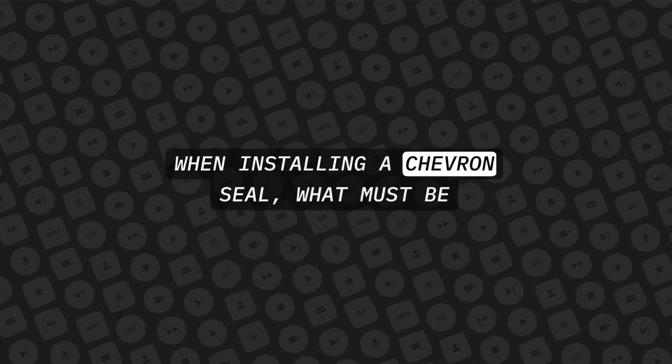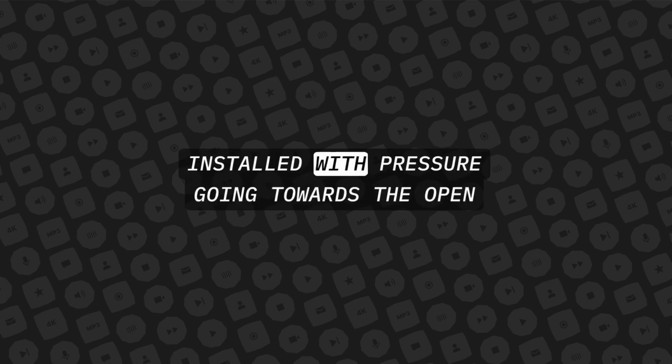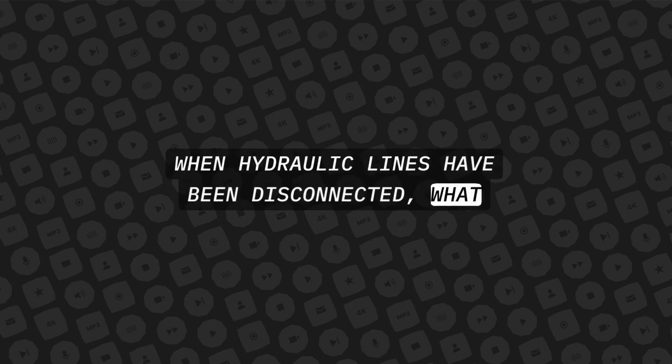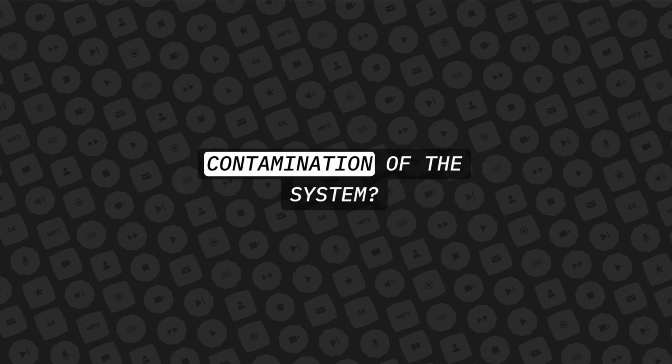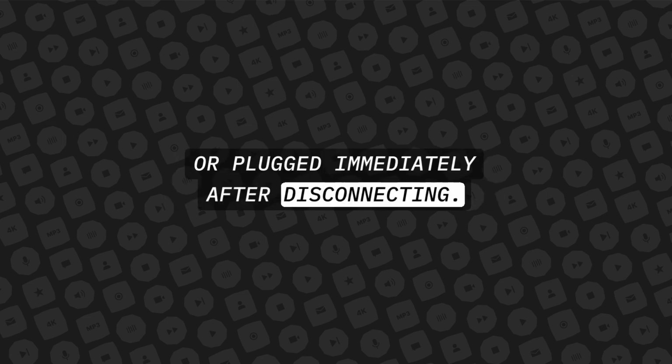When installing a chevron seal, what must be considered? A chevron seal is directional and must be installed with pressure going towards the open side of the seal. When hydraulic lines have been disconnected, what precautions should be taken to prevent contamination of the system? All hydraulic lines and fittings should be capped or plugged immediately after disconnecting.